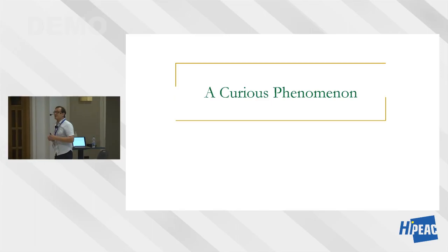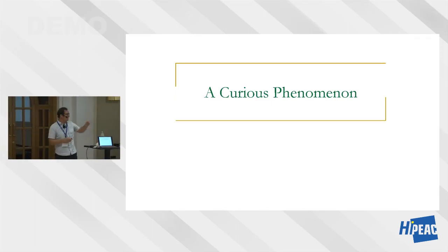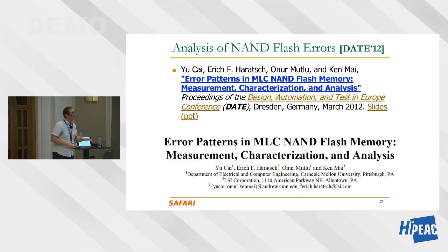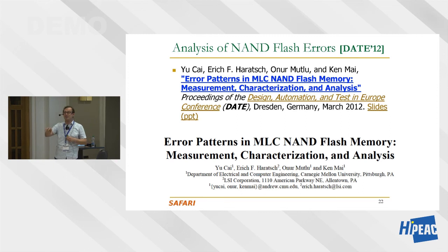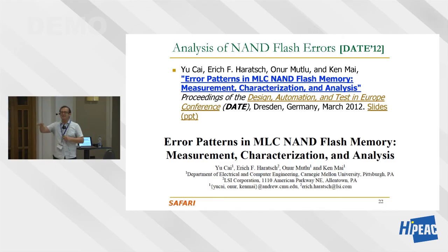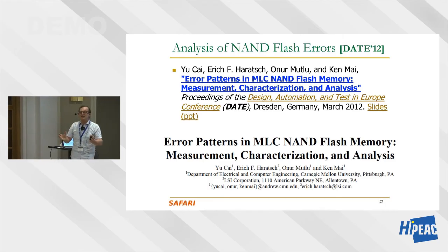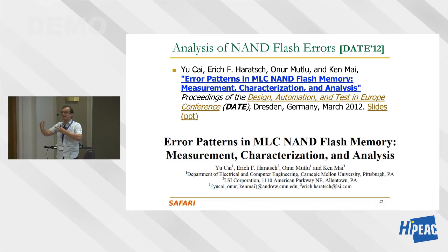So while we were doing all of this, we also asked the question, okay, DRAM. In fact, in these papers in flash memory, we saw a lot of read disturbance issues. Whenever you read a page in flash memory, you disturb other pages. So some bit flips happen. So you need to design your flash controller to fix those issues. Otherwise, you'll get bit flips in storage. But in flash memory, we have a beautiful interface, meaning that the flash controller can be designed to be completely flexible. It can do anything it wants to fix all of these issues. In DRAM, we don't have that interface today because somebody designs a memory controller and it has a very rigid interface. So we actually did a lot of studies to understand this read disturbance.